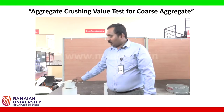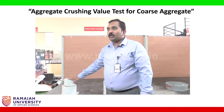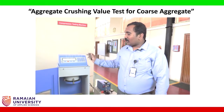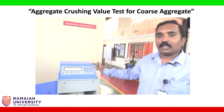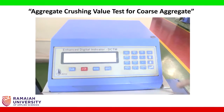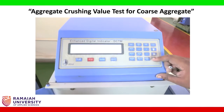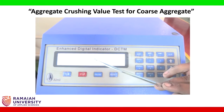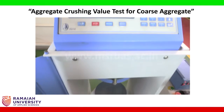Then now the test setup is ready. We are going to take this mold and place it under a compression testing machine. Now we are near the experimental procedure of doing the aggregate crushing test. So this is what we call a digital compression testing machine. There are a few operations in the digital compression testing machine. What we are supposed to do is put it in an axial mode, where the load is applied along the vertical axis.